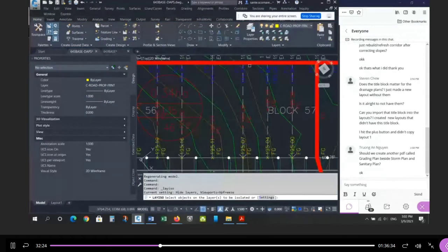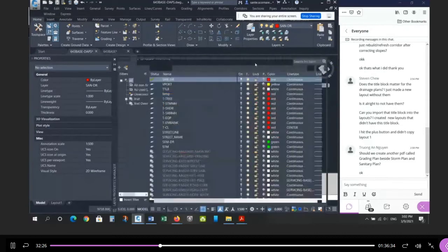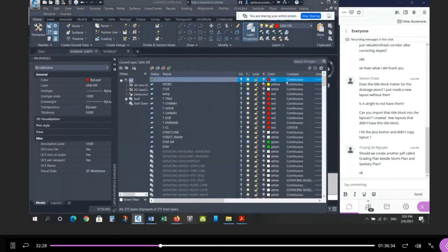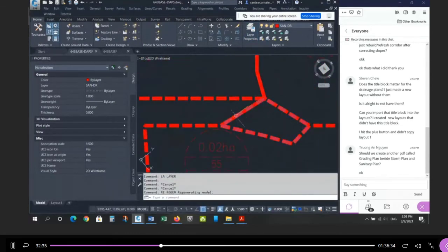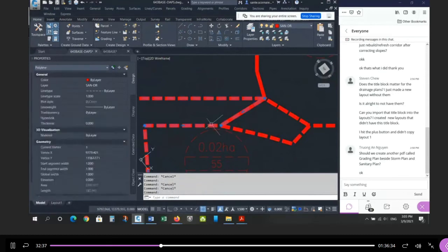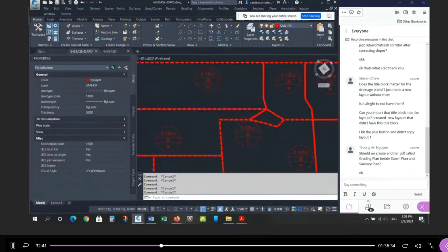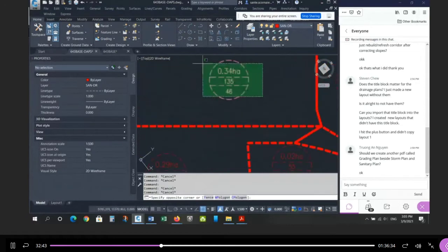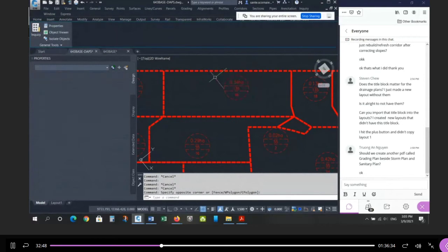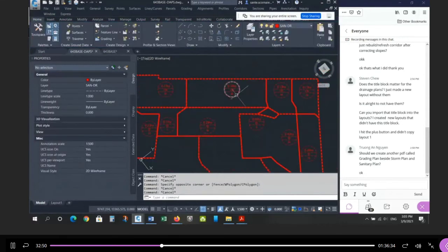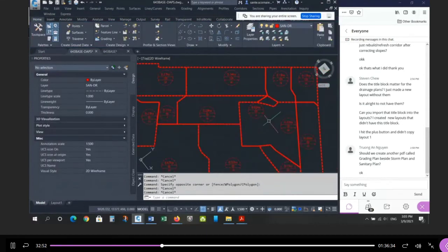Right, if I change this layer to a line type that's hidden, okay. See here, it looks like a continuous line because this pattern and this pattern are kind of in conflict with each other. You see that? So the effect isn't really that good. So you don't want these, right? And if you want, you can have these on one layer and have your label IDs on another layer. I did them all on one, but you could separate it into two. You don't have to, but it's better if you do. But I'm not going to be that picky, okay? Because it's really all just one thing, right?